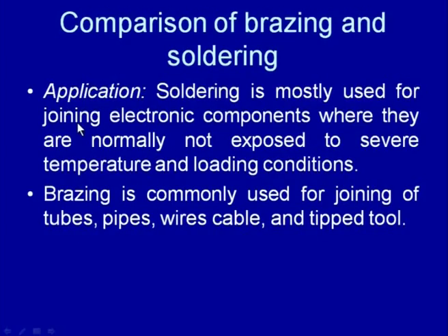Application-wise, these two processes can be compared in the sense that soldering is mostly used for joining electronic components, where they are normally not exposed to severe temperature and loading conditions, while brazing is commonly used for joining tubes, pipes, wires, cables and tipped tools, where some sort of load can act on the component or on the joint during service.